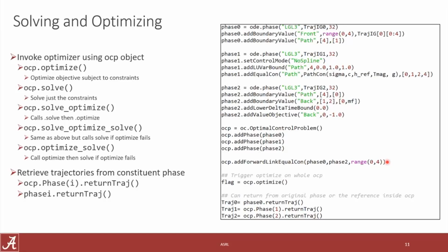Multi-objective, that then has the Earth deploy, optimizes 2 burns around Earth, does the translunar injection with a TCM, then does the close lunar flyby, and then rendezvous with an NRHO in the ephemeris model. And that will optimize and solve in less than 10 seconds, less than 5 on my laptop, not even a desktop.